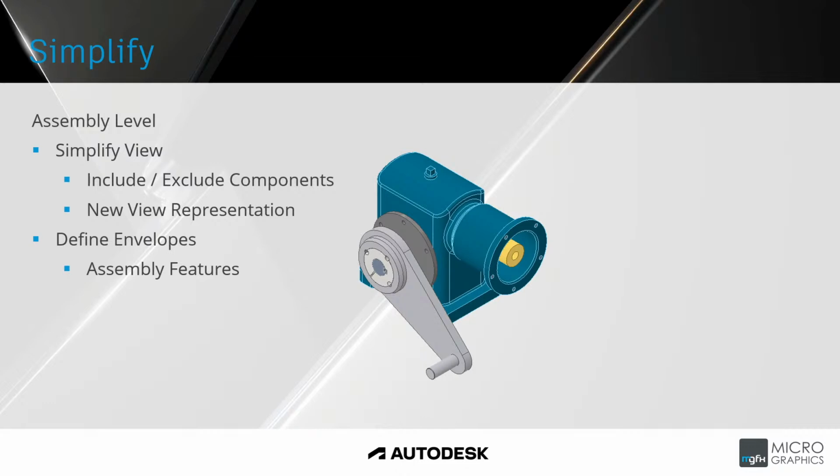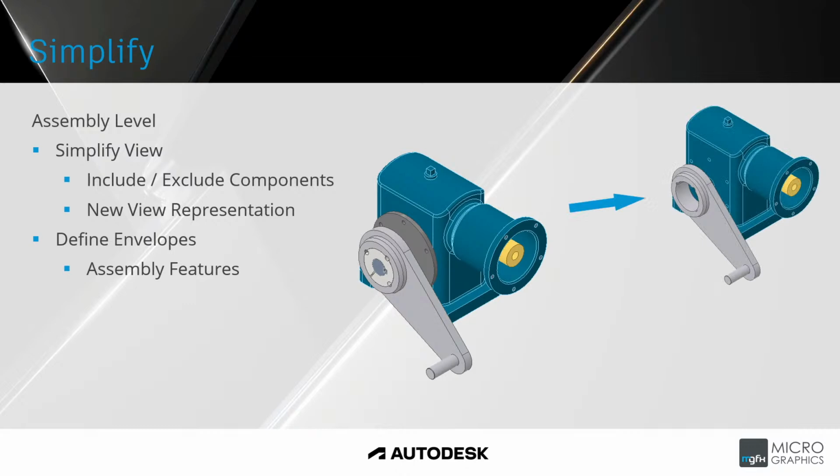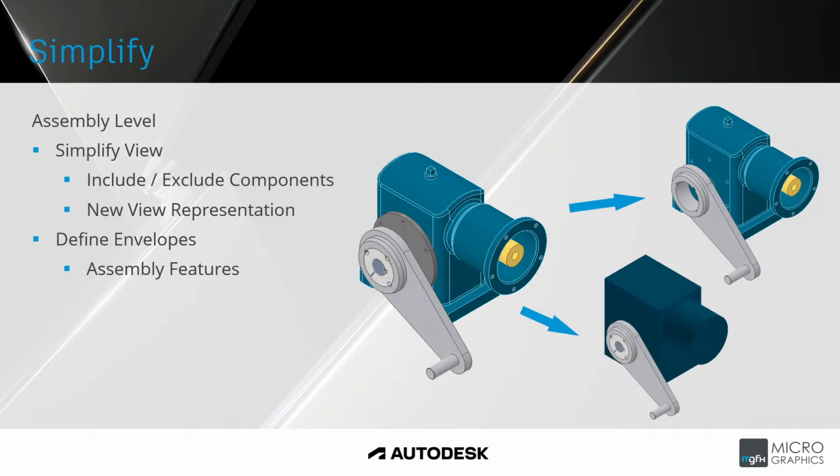Simplifying the assembly also allows you to define envelopes which are created as assembly features. So here we can see on the right hand side we have some of the components that have been excluded. You'll note there in the lever there's the large sort of flywheel that's been removed, as well as the shaft and the coupling inside of that lever, and any internal components removed as well. And once again, at assembly level, we've got envelopes defined around the gearbox housing to show the space requirement for the housing.